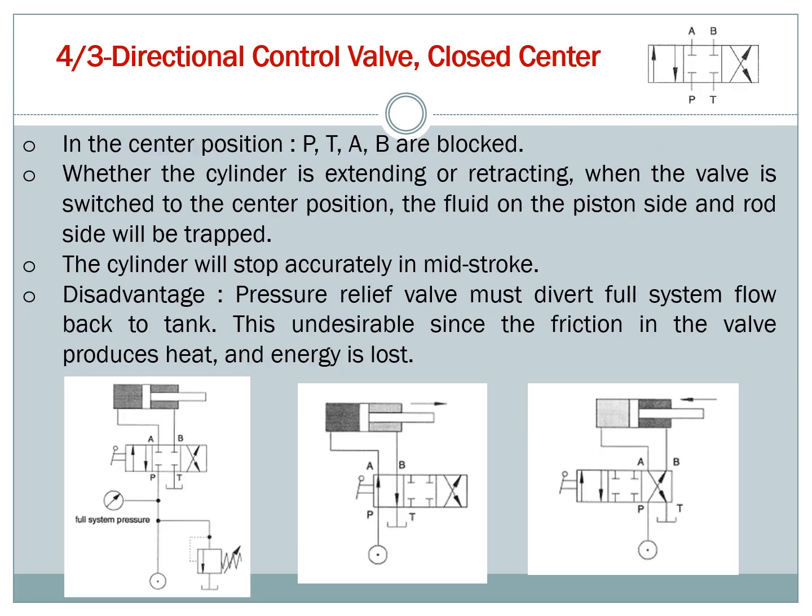Okay, so we have another type of direction control valve we call the 4/3 direction control valve, closed center. Closed center means, since you have three boxes here, left, middle and also right, the unactuated or initial condition will be in the middle.